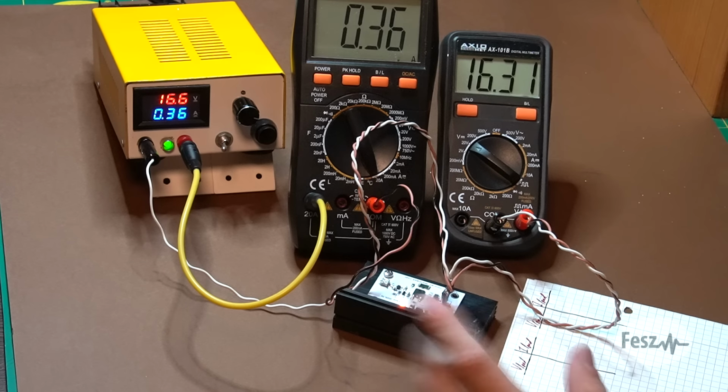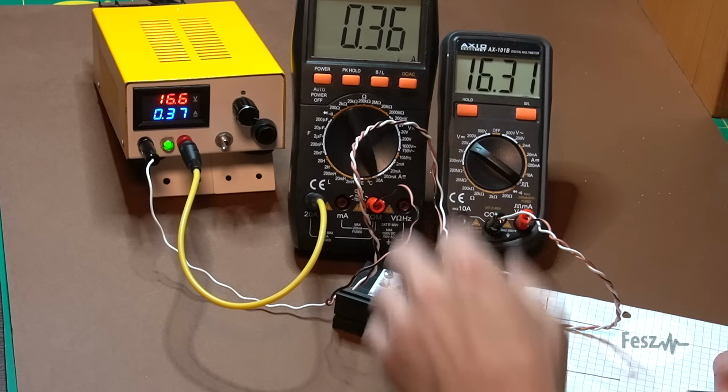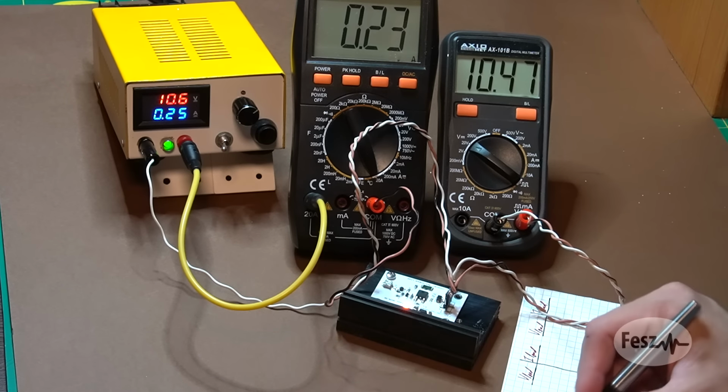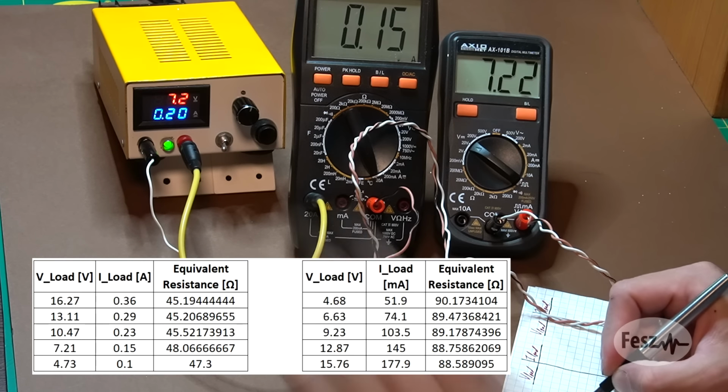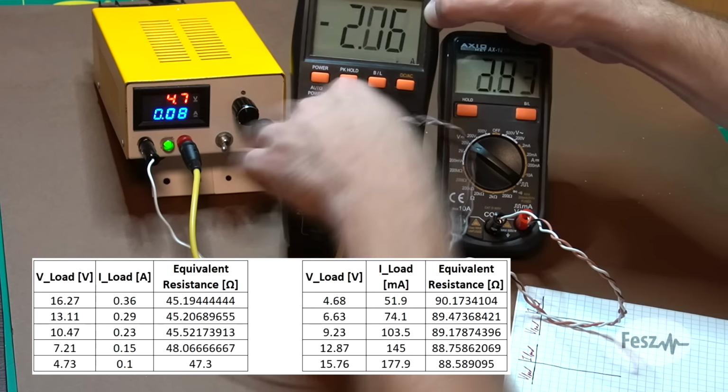Anyway, for the constant resistance load, I first used a heatsink to stabilize it, and to measure it, I used both a voltmeter and an ammeter, and proceeded to make measurements at multiple voltage points. Now, just to confirm the operation, I performed a set of calculations highlighting the equivalent resistance. So the circuit as well also seems to work just fine. Now, I had no doubt that the circuits would work. Other than a bad solder joint, the circuits in principle should operate quite reliably, especially when making a static load. They can be temperature sensitive to some extent, but it's not that bad.